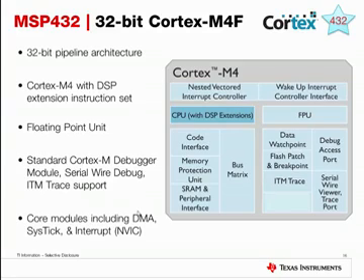So in this particular Cortex-M4F flavor that was chosen by MSP432, the device also includes a nested vector interrupt controller, or NVIC. It also includes an FPU, floating point unit, as well as the enhanced DSP instruction set that comes with Cortex-M4. From the debugger standpoint, it features a standardized Cortex-M debugger module, serial-wire debug, as well as ITM trace support. Since this is a Cortex-M4F core, it also inherits a number of peripherals that come from the Cortex and ARM family, including the micro DMA, SysTick, as well as the interrupt controller, as mentioned before.